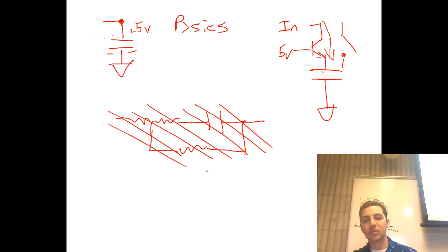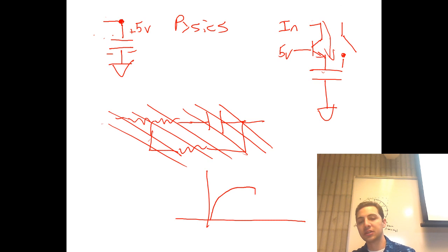So if you think of how a capacitor charges up, it charges up kind of like this, and it'll discharge kind of like that. Looks like a surf wave. So what we have to do for this type of RAM is actually refresh this RAM periodically by reading it. If you read it over and over again. This is not a real DRAM circuit, by the way, a real DRAM cell.